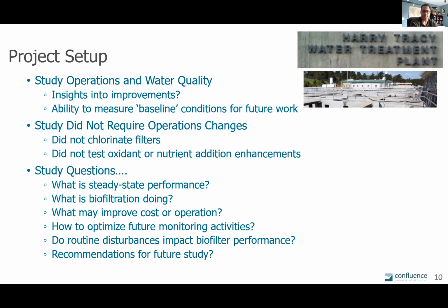So you see it at the top there, the ozone process, before and after ozonation, the coagulation process, before and after coagulation, and you'll see that term AWWA on the right-hand side of your screen. That's what they call their flash mix and flocculation channel, the applied water channel before going to filtration. You might see that acronym later on.